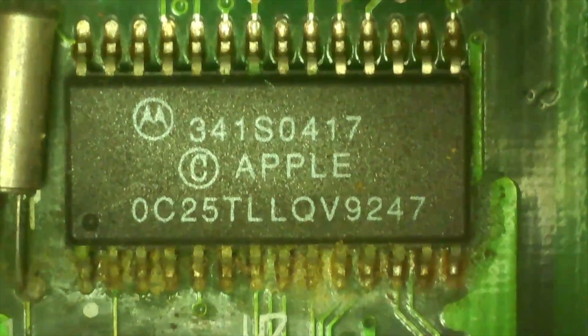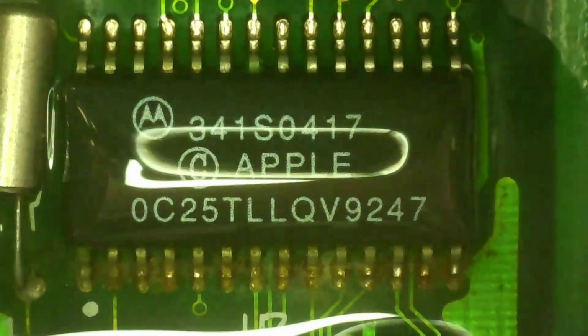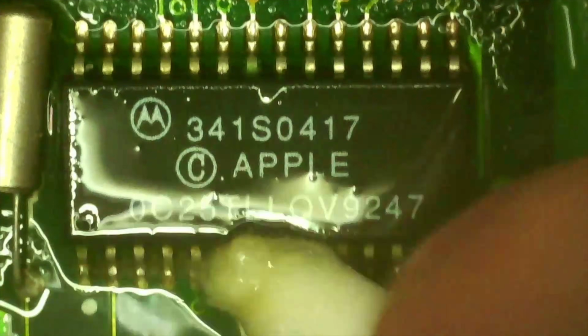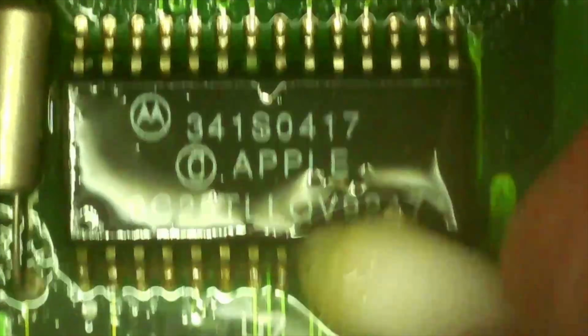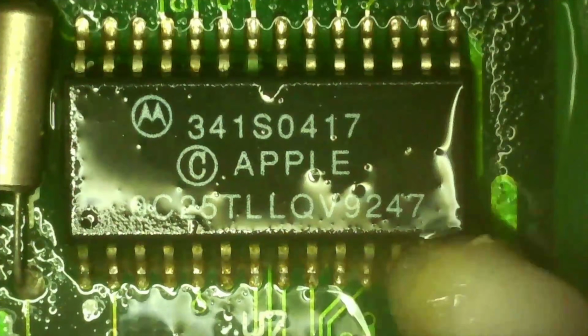Now that the caps are off, we can take a closer look at the board and see that they've left a lot of goo to clean up. This is the CUDA chip, a glue logic chip that's essential for operation of the machine, and you're not going to easily find a modern replacement, although efforts are underway to change that. If cleaning this thing up doesn't work, we're dead in the water. I'll go ahead and clean it and reflow the solder joints and see if that gets us where we need to be.